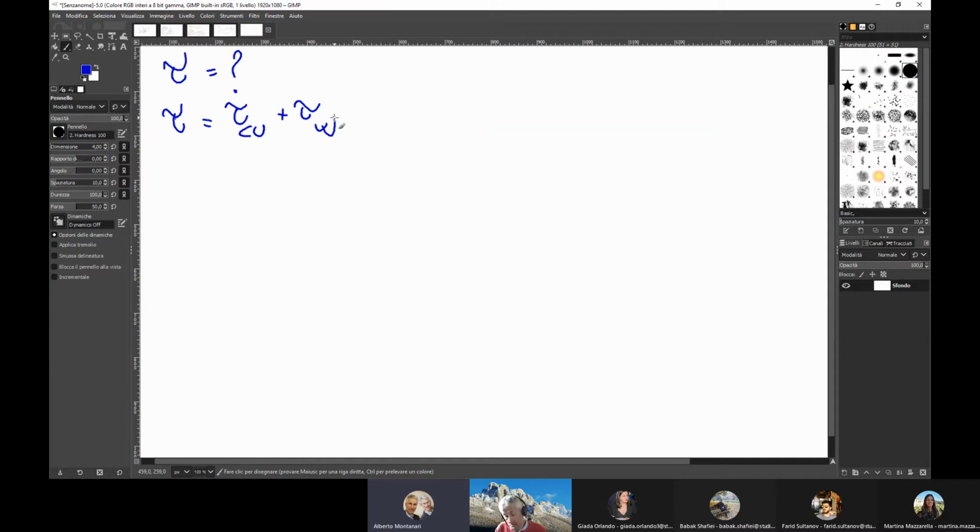It's the movement of water relative to the surface. If it's the groin, it's movement of water along the side of the groin. And if it's sea bottom, it's movement of water with respect to the sea bottom. And so the shear stress is originated by the velocity of fluid particles that are moving with respect to the opposing surface.